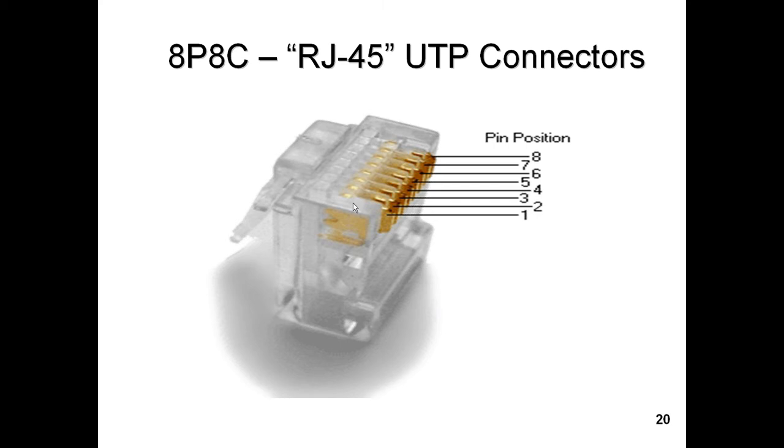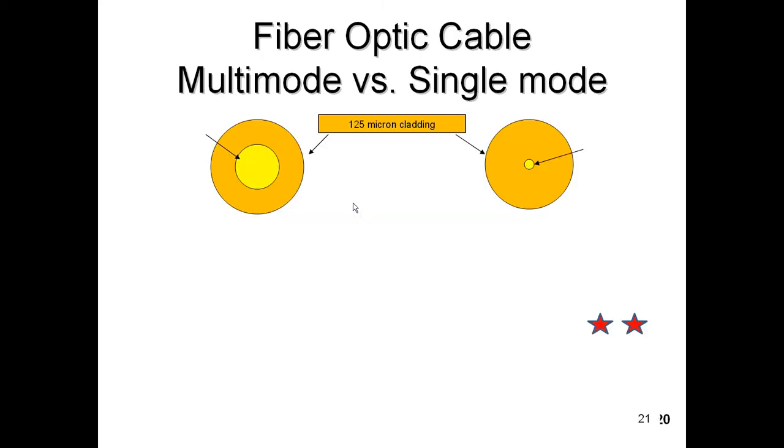I like that termination kit because you push the wires all the way through the jack, so that when you crimp and cut with the pliers-like tool that crimps it and cuts it, you know that your conductors are going all the way through. I don't like the jacks where you have to trim to length and then try to get them to fit in. It's not a good idea. Get that EZ RJ45. That's the best one that I've seen to do terminations on a UTP cable.